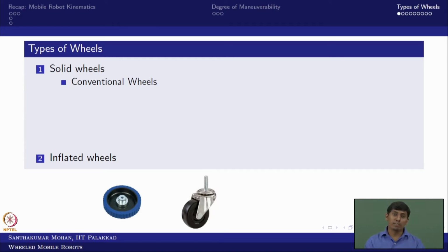Now what would be the difference between conventional and non-conventional? You know conventional means it's pure rolling. There is no lateral slip, infinite resistance offered in the lateral direction. Now you want lateral direction motion. So then what one can see is, you take the fixed wheel and put a passive roller on the bottom.